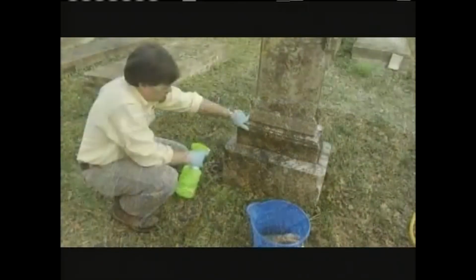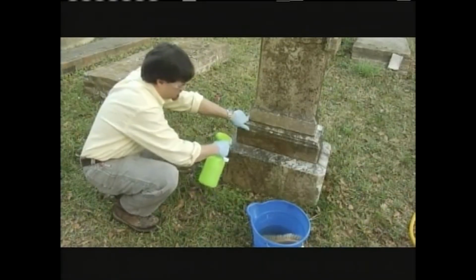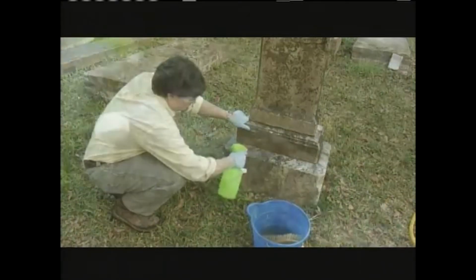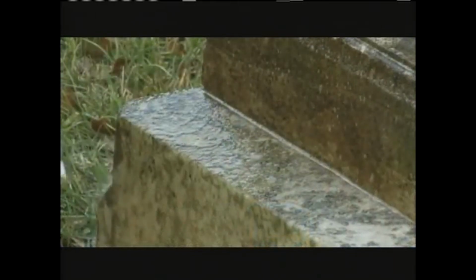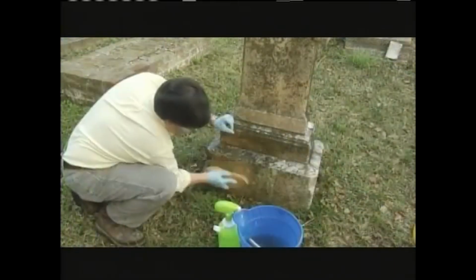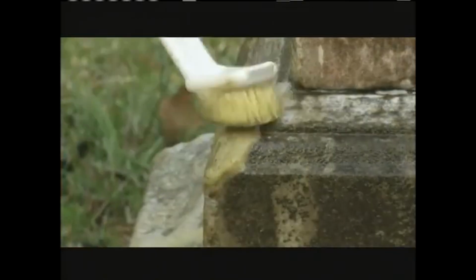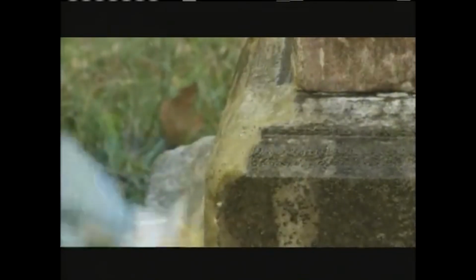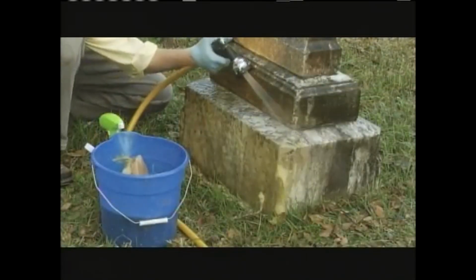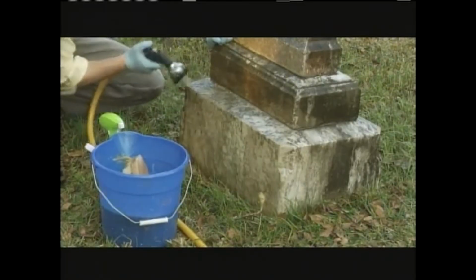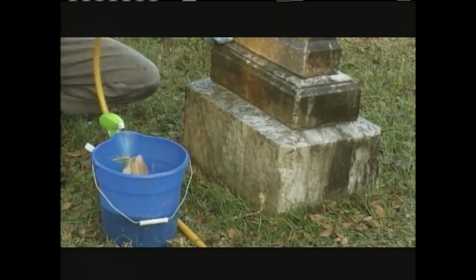Once it's wet, we start cleaning from the bottom and slowly work our way up to the top. Starting from the bottom of the stone minimizes streaking and staining. We're going to want to use small circular motions as we go. This helps to get in all of the crevices. Sometimes it's important to switch brushes to meet the situation. On stones with a lot of biological growth or heavy soiling, you may need to repeat the cleaning methods more than once.